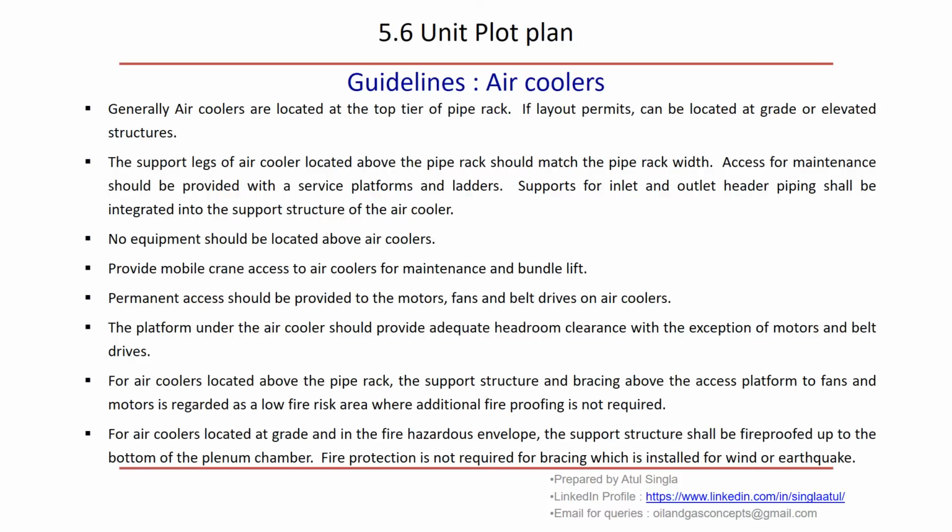For air coolers located at grade and in a fire hazard zone, the support structure shall be fireproofed up to the bottom of the plenum chamber. Fire protection is not required for bracing. Here also we don't go for fireproofing of the bracing, which is installed for wind and earthquake purposes only.